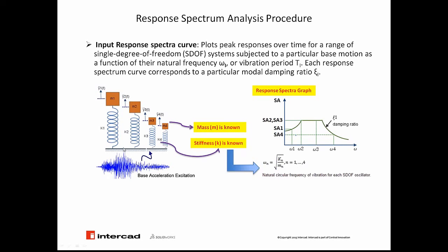Then under such a loading, with the known values of m and k, we measure the response, and that is the y-axis. So if you have the response spectra graph, meaning the peak response of the structure to a dynamic loading, then in response spectrum analysis, we enter such a curve into the analysis and combine the effect of these peaks with different methods, and look at the maximum response of the structure while such a loading is applied to the structure.